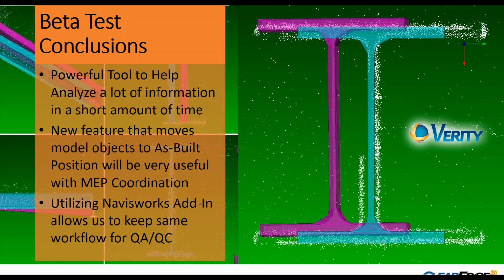And even when we do color scans, at level 2, 1,000,000 points a second, at 2 millimeters as our error rate, we're still getting 4 to 4.5 minutes per scan location, so it is extremely quick. As for Verity, it does not take a lot. They've actually told me to turn down the sampling rate when you're taking the E57 files out to Recap.